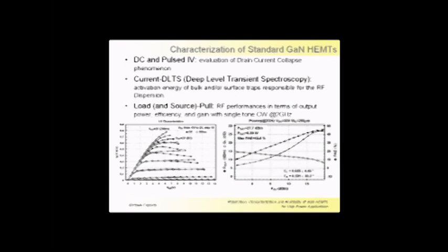This means that the DC to RF dispersion effect has been killed by silicon nitride deposition, and moreover, there is a self-heating effect reduction.